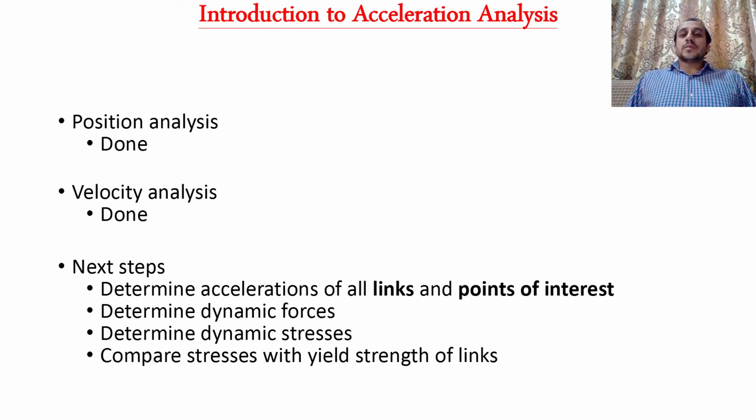So what is the purpose of this whole process? So that we can determine the dynamic forces using the formula F is equal to ma, where F is force, m is mass and a is the acceleration. So we are calculating the accelerations. What is the purpose of calculating dynamic forces? The purpose is to determine the dynamic stresses, because if we know the dynamic stresses when the mechanism is in motion, then we can compare that instantaneous stress level with the yield strength of the links.